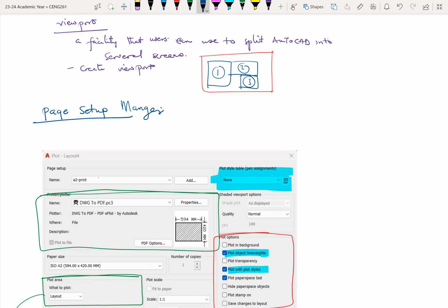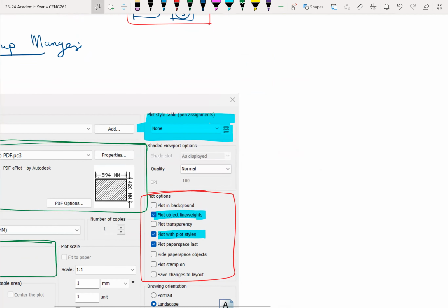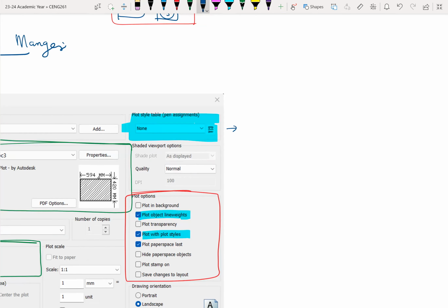And then here, when it comes to the pen assignments, just like how we have in technical drawing, where when you are drawing, you use 2H pencils, HB pencil, 4H pencils, depending on which part of your drawings are critical to you, so that the most important aspects are more visible and thicker in terms of their line weights. We also apply something very simple, something similar to that in AutoCAD, right? So usually you find the pen styles, I think there's one called Acad.ctb.